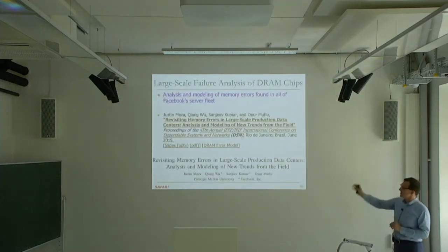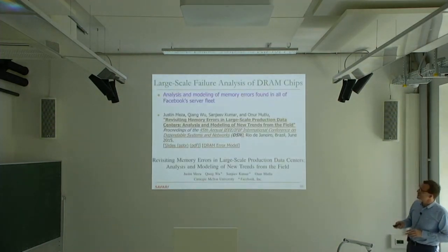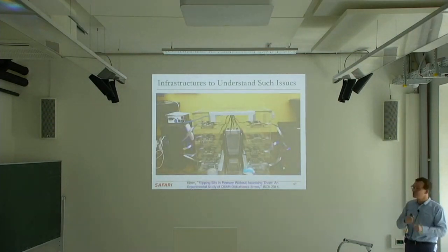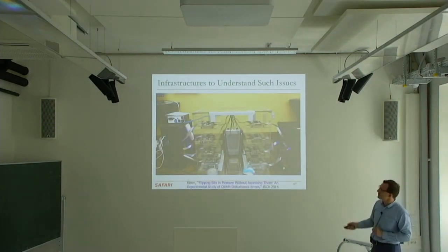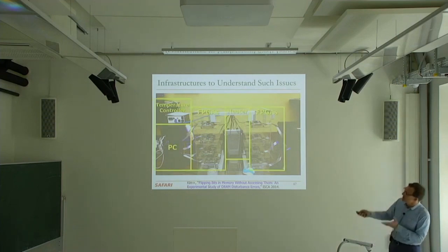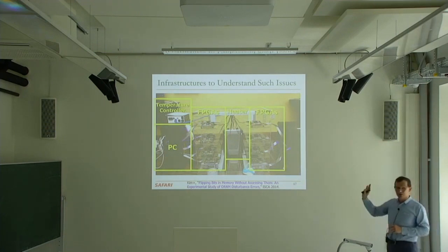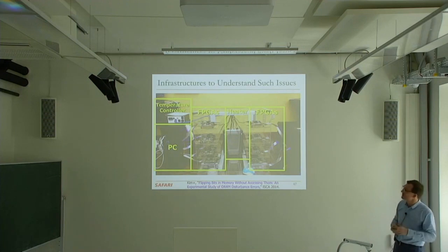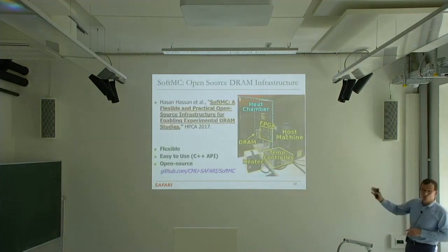Okay, so this is one example. We've been studying these scaling issues also at the small scale in a more controlled way. Here we have our FPGA-based infrastructure. Each of these FPGAs is running a memory test, and you can control the memory test with heating and temperature. We're going to talk a lot about this infrastructure to understand the scaling issues. And we actually open source this infrastructure.